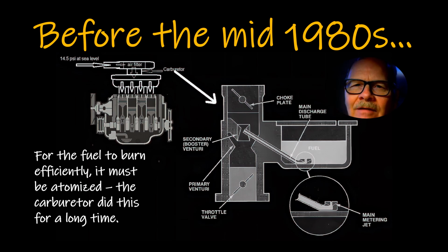And so what you'll have with that is some of the fuel doesn't burn and it remains on the head of the piston and on the cylinder head. Over time, the rings will wipe it off the cylinder walls, but over time, that turns into crusty carbon junk that takes up space in the combustion chamber.